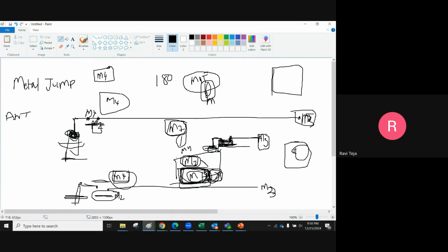Now if I use M4, what happens is, this is the gate, this is M3, this is M4. Now there is no M2 here. So there is no M2 here, we are using M4 now. So now if there is any charge on this M3, you can remove this M3 before fabricating M4, because this is an open circuit, there is no closed path, right?